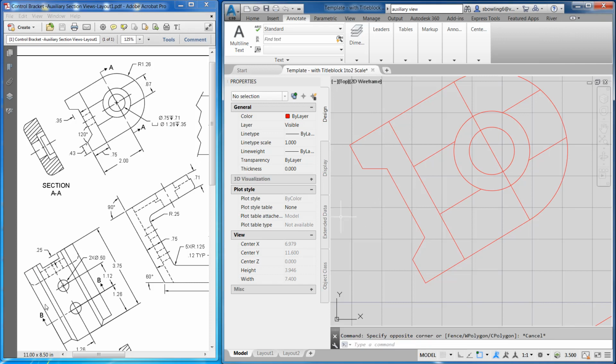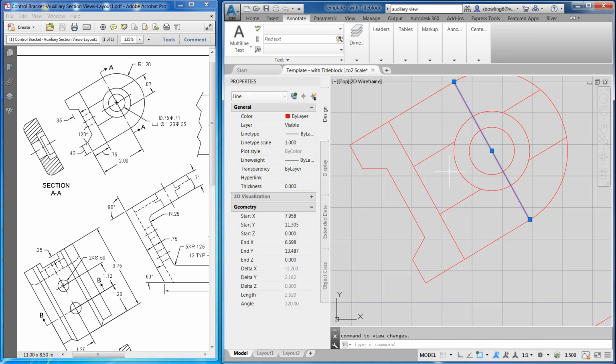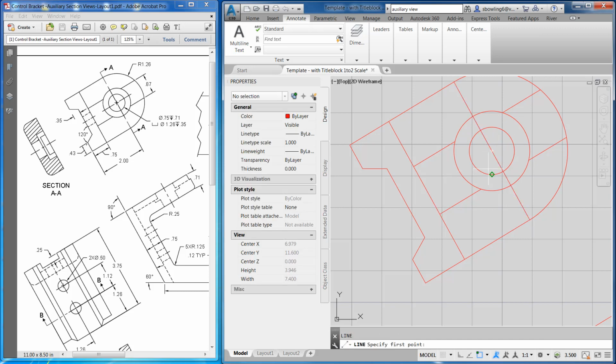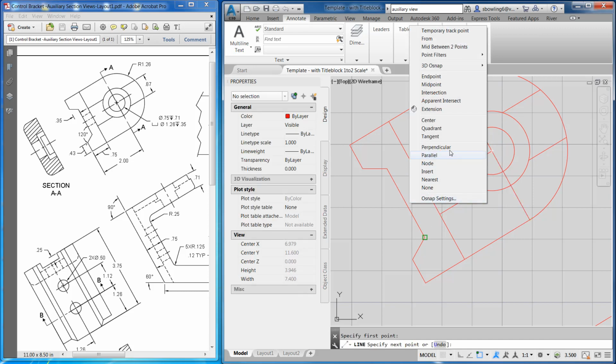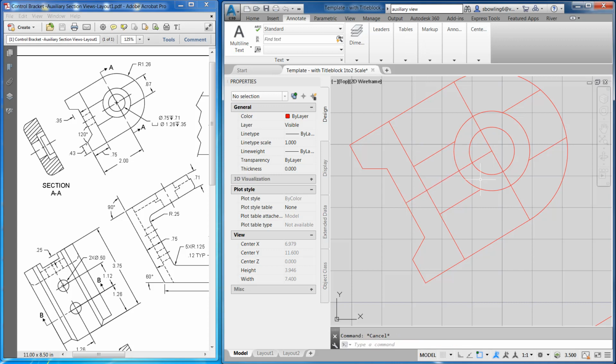So now I'm just going to draw, because it's 1.6 in, and basically that's the center of this line. So I can draw from the center, shift perpendicular. And remember what I did with these? I'm going to just offset, well, that's easy enough. That's offset a quarter. Offset 0.25. So we can go, actually I'm going to trim this up.